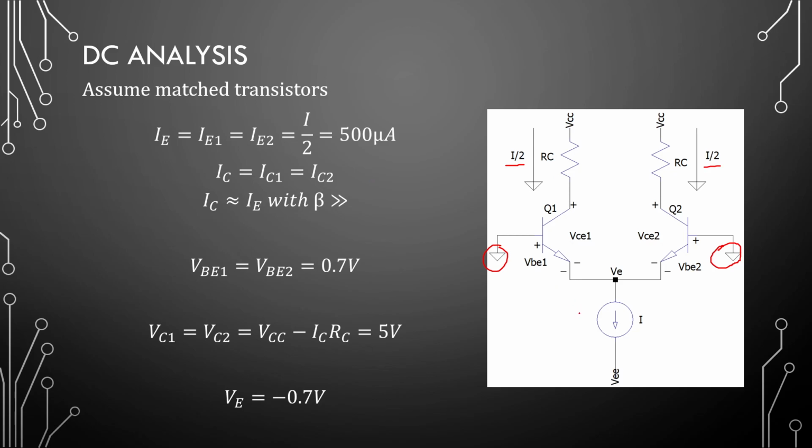So in maths, we have the emitter current down here being driven by a current source, so the two emitter currents will be equivalent, and with a large beta value our collector currents will be equivalent. So large enough beta, don't care about the little bit that gets lost here at the base.